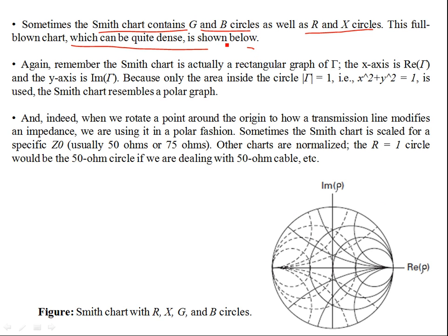But it depends on your choice. If you want to make calculations with both impedance and admittance, for example when designing a stub matching, where you add series or shunt stubs and move along constant resistance circles, you don't have to rotate the chart again and again. You can use both the G and B and the R plus X circles to your advantage.